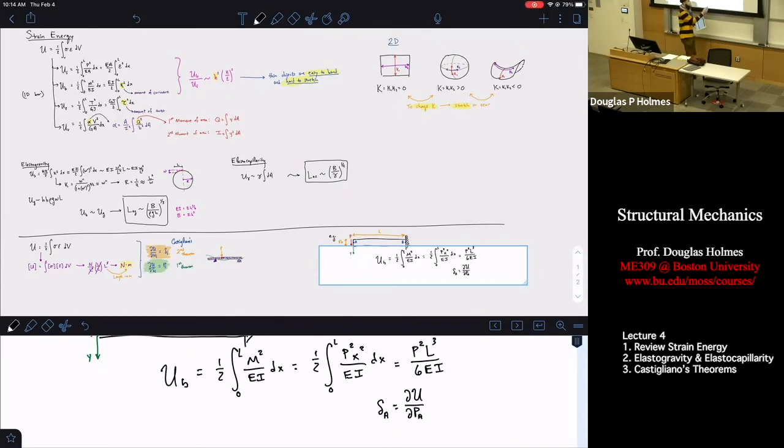The key thing here is that the subscript on the force and the subscript on the deflection are the same, which means physically that the deflection we're solving for is at the point that the force is applied, but also, and this is hard to show in this notation, that the deflection is in the direction that the force is applied. The force is going down, the deflection has to be going down too. Now we said, well, let's approximate our strain energy as an energy that only has bending.